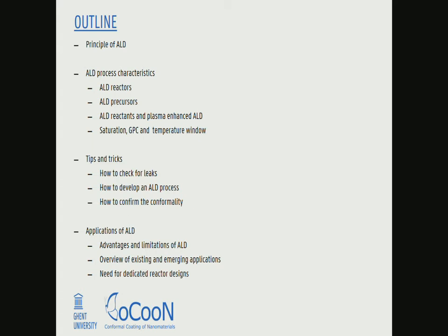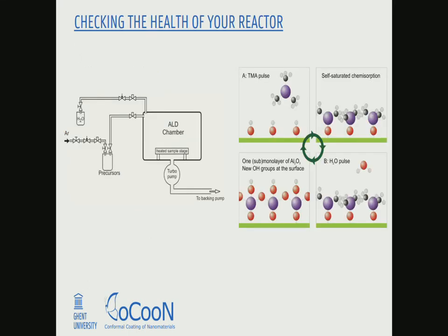Maybe more quickly, some tips and tricks if you plan to do ALD in the near future yourself. Whether you're using a home built or commercial reactor, if you want to be sure about the status and the health of your reactor, it's always a very good idea to have TMA attached to it. And if you want to be sure that there are no leaks or no funny things going on with your reactor, you just put in a sample. You give 100 pulses of TMA, but no water. And then in principle, if all goes well, nothing should have grown.